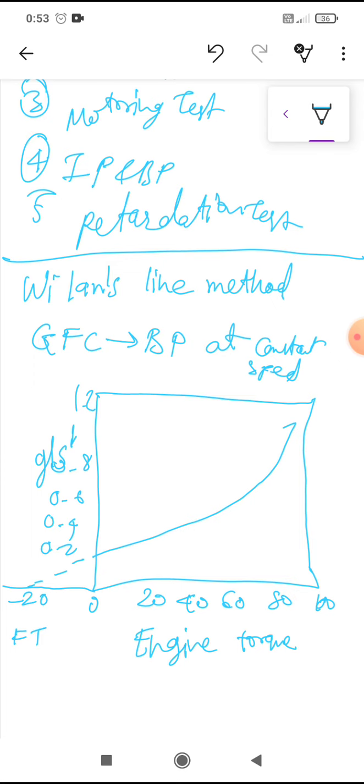Now, what are the drawbacks of this method? The drawback is the long distance to be extrapolated from data measured between 5 to 40% load towards the zero line of the fuel input. The directional margin of error is rather wide, because the graph may not be a straight line many times. So a changing slope occurs. The changing slope along the curve indicates part efficiency of the increments.